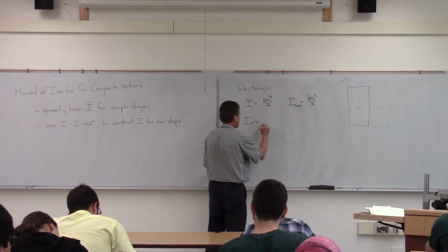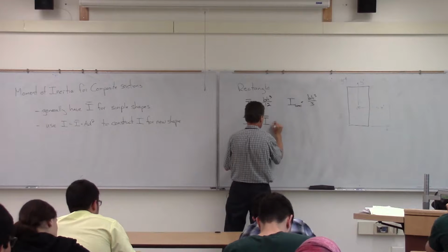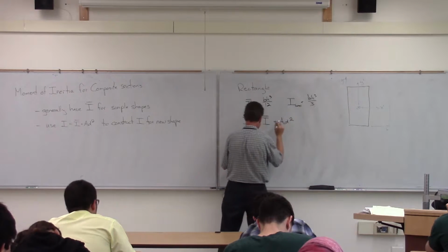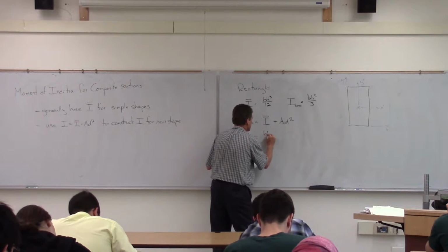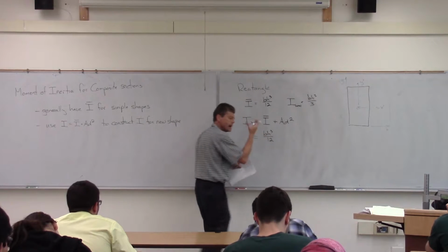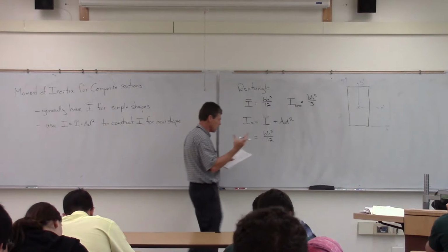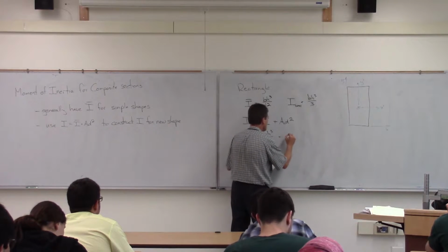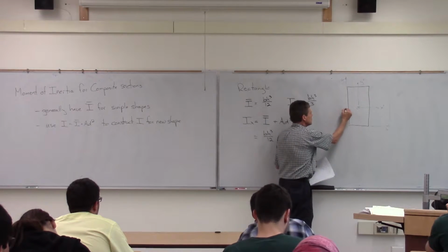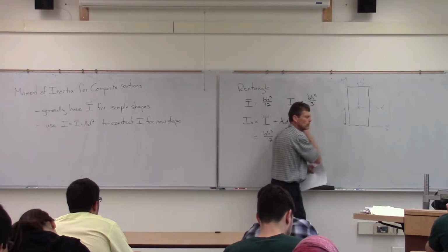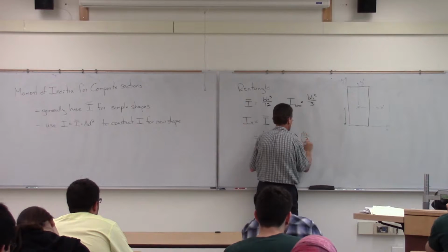So solving for Ix, I put in my I bar that I know. That's the thing generally I can pull out of the book or the text or Steel manual or whatever. Area is going to be BH. And then G is going to be this distance here. It didn't show up too well, but basically H over 2. But it's squared.